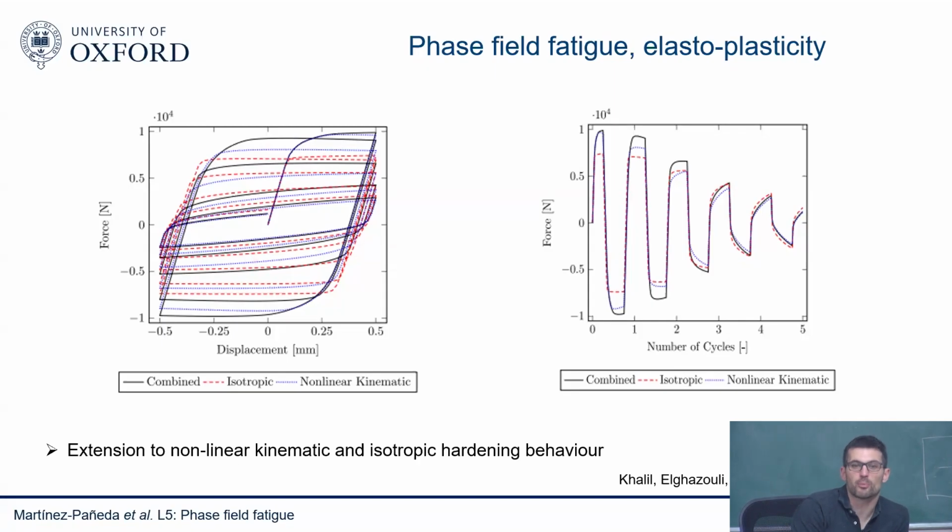We normally take this approach where we assume that only a percentage of the plastic work is stored. But when you're talking about fatigue, a lot of the community that do crystal plasticity and so on typically consider the stored plastic energy only, because they say it dominates completely the behavior ahead of a crack. So the picture becomes a bit more complicated, and there are some choices one has to make.